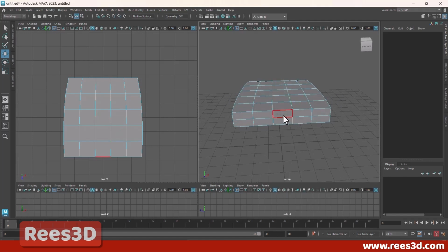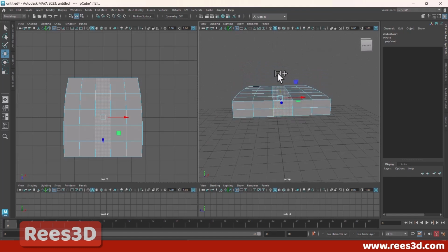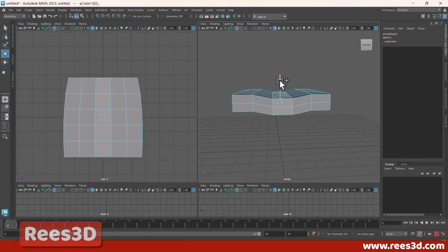So if I just select these faces, I'm going to press the shift key and double click on the second one, so you can see that it selects all these faces down here, and I can just click and drag. So this again creates the same exact result. Okay, so it doesn't matter whether you're using a vertex or edge or face. If you know exactly what objects need to be moved, you need to select them and it would do the trick. Okay, so I'm just going to leave it as it is, something like that.